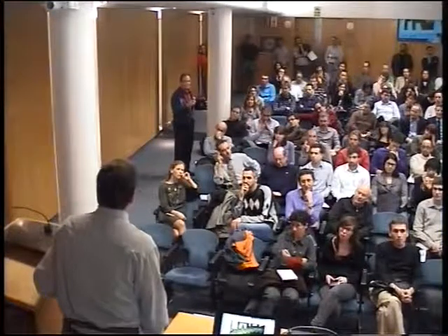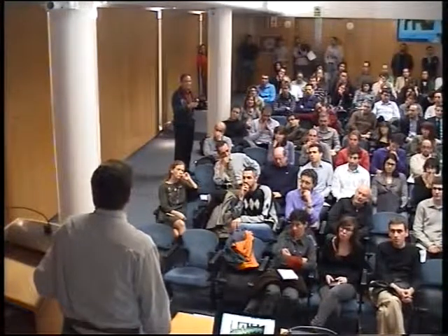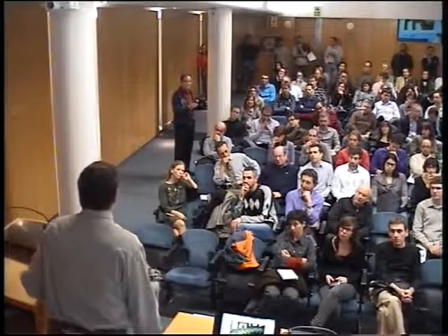Up to 5% is a little bit high, but for a somewhat lower slope, but also a steep river, I suggest you talk to Carlos and Juan Pedro, because Carlos' thesis addresses these issues with a very nice morphodynamic model of the effect of gravel mining on river profiles. And the particular model they have developed can be used to design various rates of gravel extraction at various locations and test what the response of the river is in order to try and find allowable amounts of sediment removal.